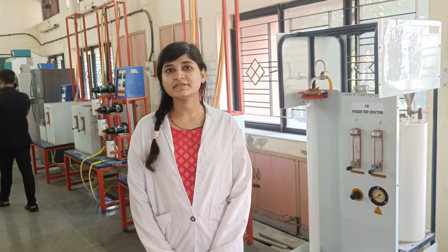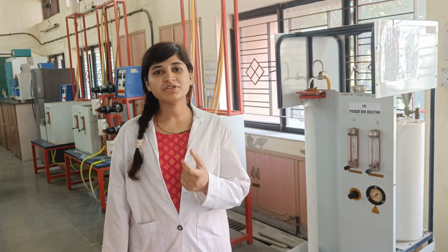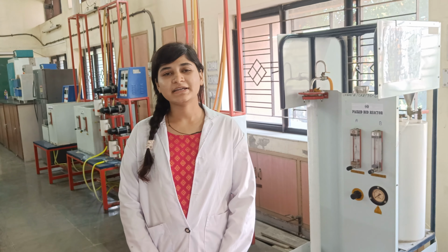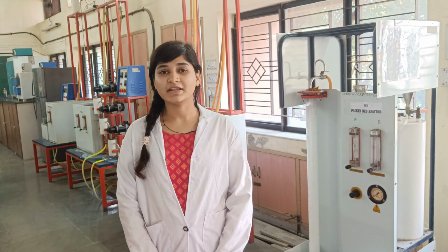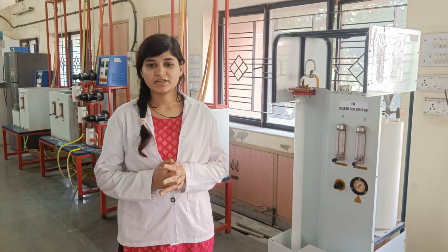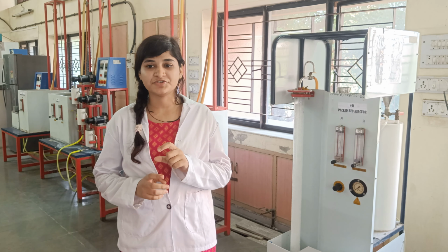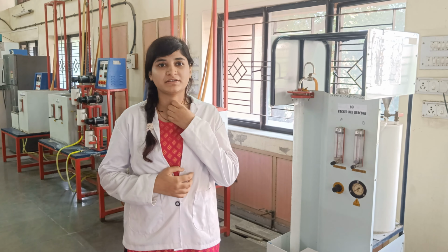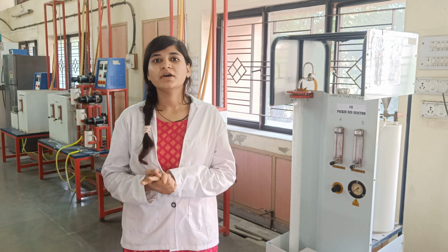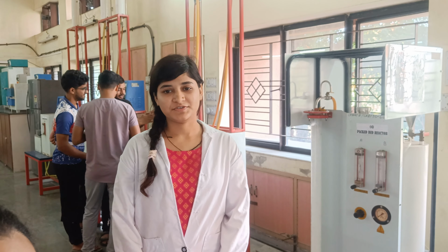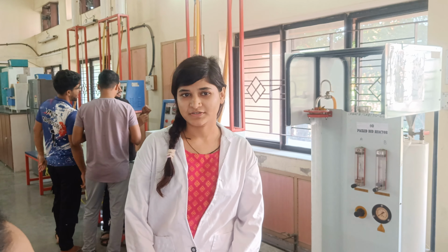Here we will discuss advantages. Efficient use of catalyst. The solid catalyst in a packed bed reactor provides a large surface area, leading to high conversion rates. In optimized conditions, packed bed reactors can achieve high conversion efficiencies for saponification reactions as compared to plug flow reactors. Those are the advantages. Now let's move on to the disadvantages.